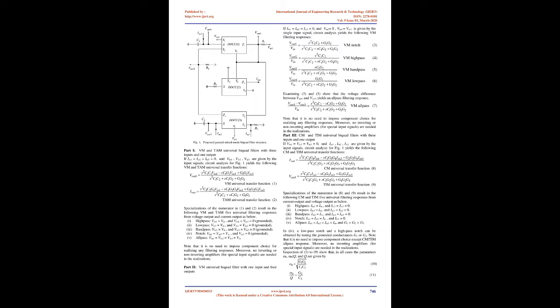In [13], Li and Chong proposed a single FDCCII-based mixed-mode biquad filter [13]. The circuit [13] uses only a single FDCCII, 3 floating/grounded resistors, and 2 grounded capacitors. In 2017, the reported mixed-mode biquad filter [37] employs only a DCDA and 4 passive components. Although single active element-based mixed-mode biquad filters have been proposed in [13, 37], both circuits [13, 37] are not general mixed-mode universal filters. Moreover, both used active elements, i.e. FDCCII and DCDA, are complex active elements.